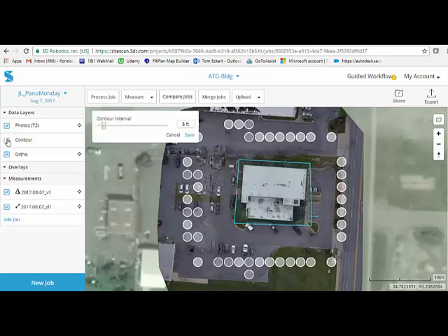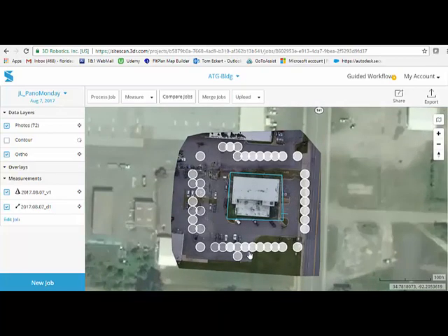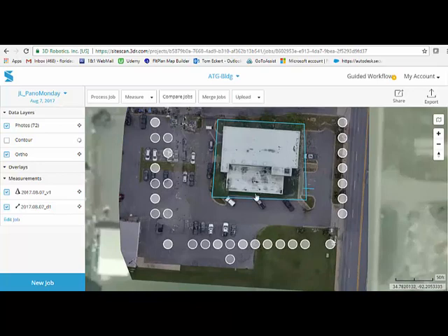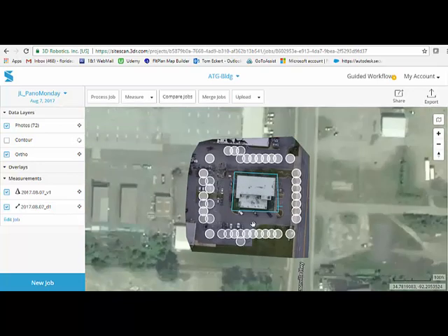When we would maybe want to use contour data, let's go to a 1-foot contour and say, in this spot, let's actually use the contours for the site. Now, what does that mean? Well, it's going to contour up the side of the building. We can pull those out. But it's also going to contour the site itself. When you're at 175 feet and the gimbal is focused at a 60-degree angle of incidence, then you will get both the building model, the roof, and the site plan. And that's the beauty of the panorama feature.